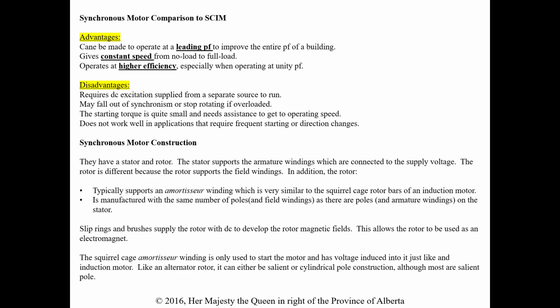They may fall out of synchronism or stop rotating if overloaded. So we have a maximum load, or it will actually rip it out of synchronism and stop the rotor potentially from spinning. The starting torque is quite small and needs assistance to get to operating speed, and does not work well with applications that require frequent starting or direction change. So again, we can see that the starting is a bit of an issue for these guys.